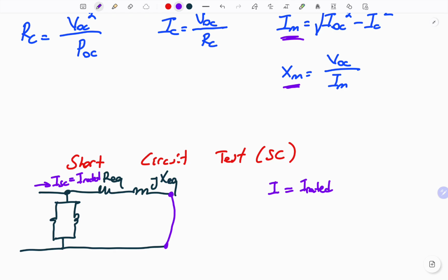Because of the short circuit condition, we have smaller voltage values at the input side. Generally, it will be 20-25% of the normal rated voltage value of the transformer. In addition to that, we can also measure the short circuit power value to determine the parameters. Which parameters? For this case, instead of 0 secondary side current, we have the rated current.